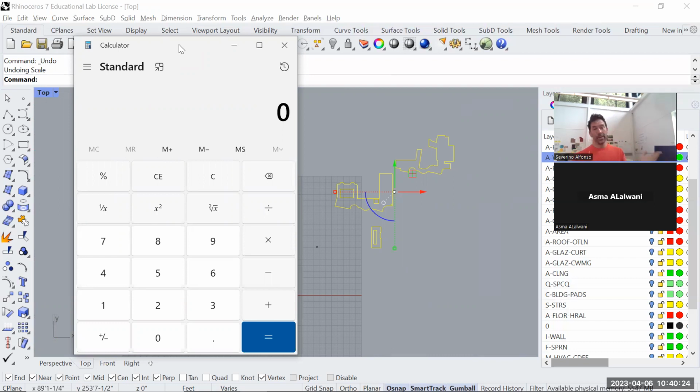You create a paper space in AutoCAD. So you bring these lines to AutoCAD. You create a paper space that is the same size as the sheet that you're going to laser cut. Fit all of them there. Make sure that this doesn't happen, right?